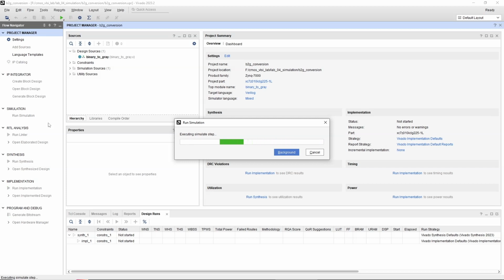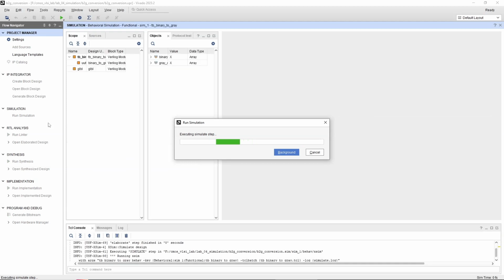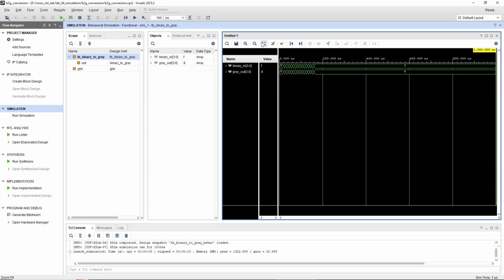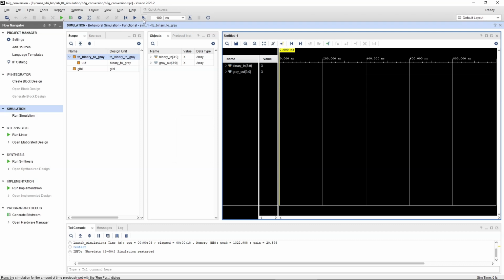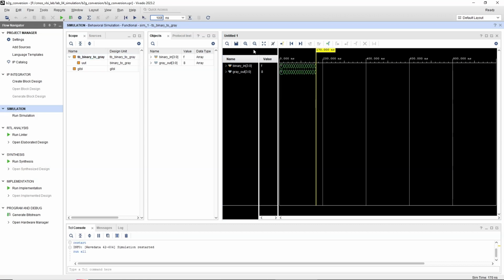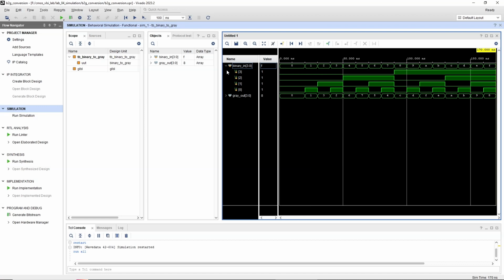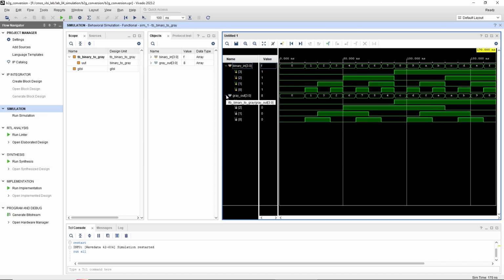After the simulation runs, use the waveform viewer to inspect the results. Verify that the outputs match expected results based on the input scenarios defined in your Testbench. You may be required to restart the simulation to see the waveform within the required time frame. After restart, set the simulation time and click the Simulation icon. Click the Zoom icon to see the complete waveform.